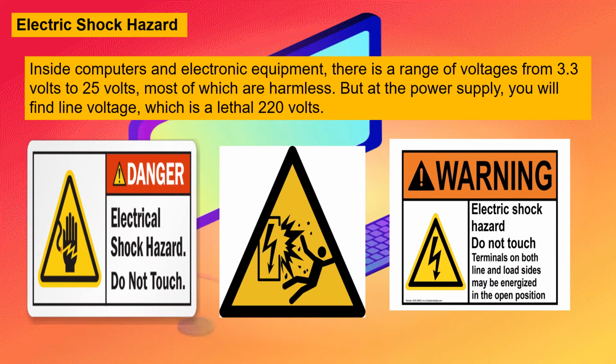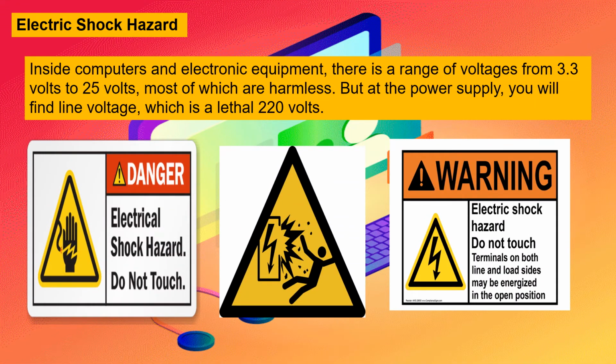Electric shock hazard. Inside computers and electronic equipment, there is a range of voltages from 3.3 volts to 25 volts, most of which are harmless, but on the power supply, you will find line voltage, which is a lethal 220 volts.